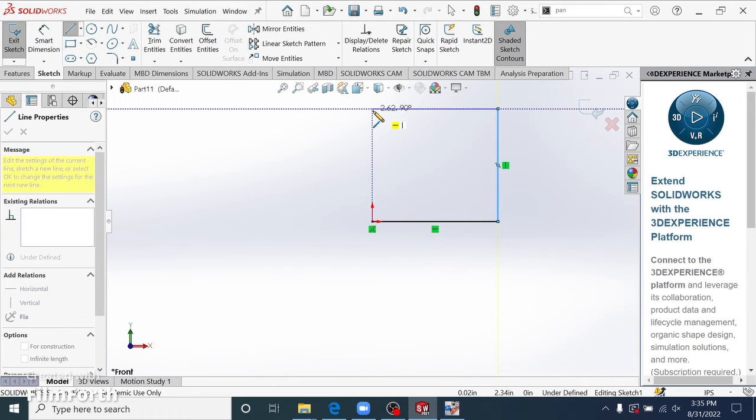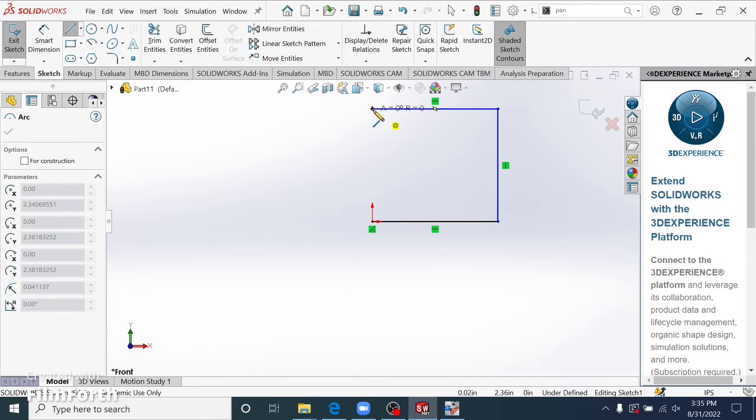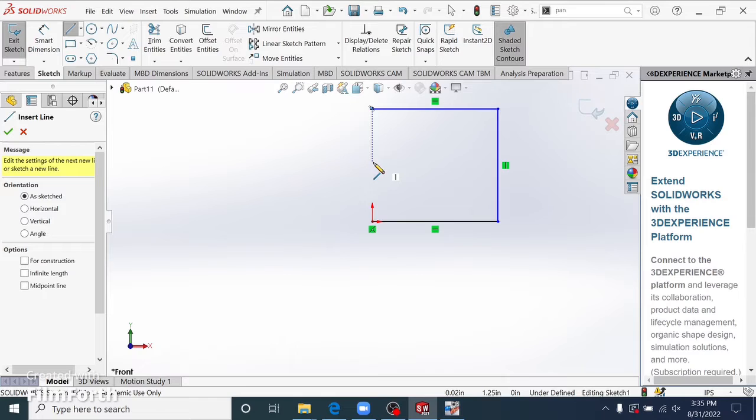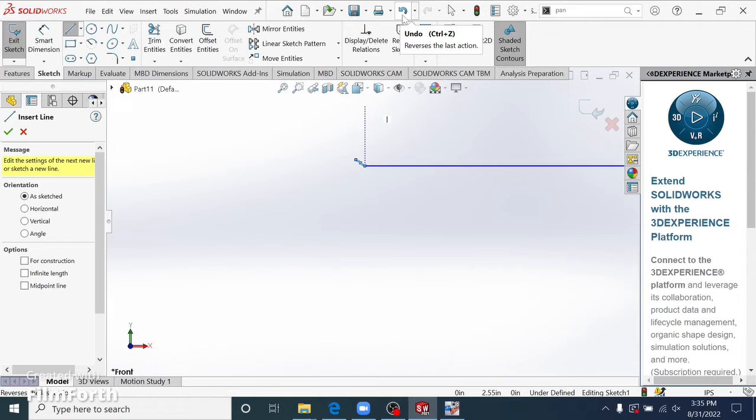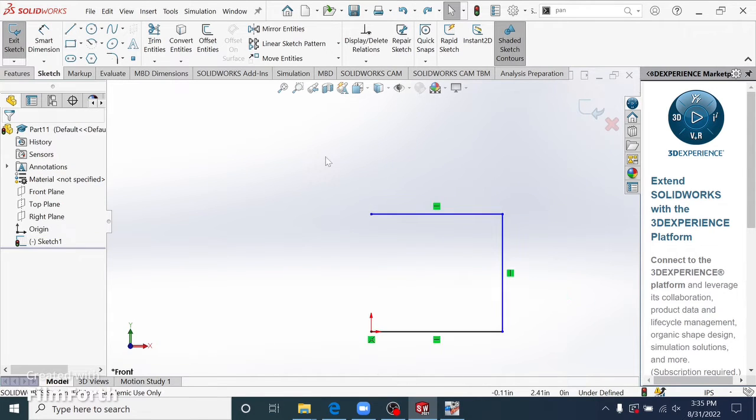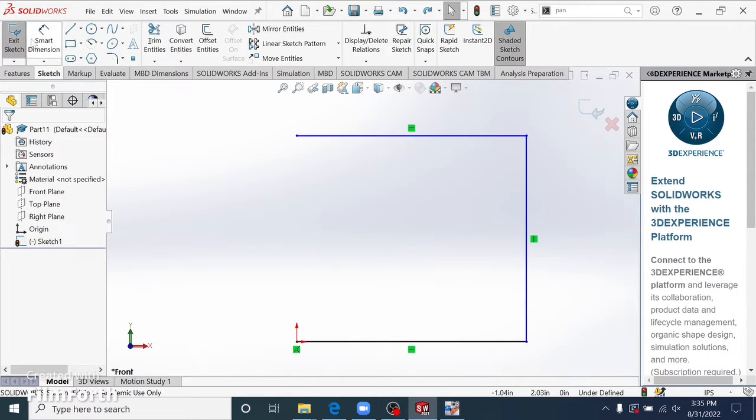And once that's already locked in, click right there around that region. Don't worry, it'll automatically lock in right away. And I want to cancel it right here at the point right here. So once it turns orange, you'll see it'll be orange. Just double click it. And that's how you click your cancel command. And you notice that there's a little small tick right there. So I'm just going to undo it. That way it'll just remove that one. That's it. So now I'm going to use my smart dimension.